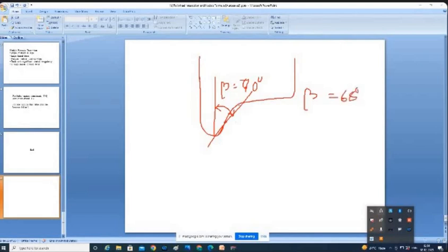Whenever this angle becomes 90 degrees, as the wheel set moves over the rail table, the 68 degrees will become 69, 70, 71, 72. It will keep on increasing. So finally it will reach a stage that is also called as sharp flange.